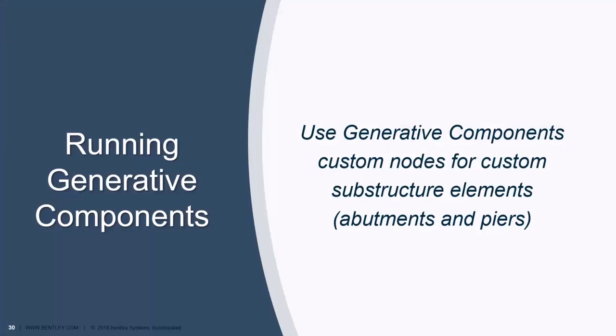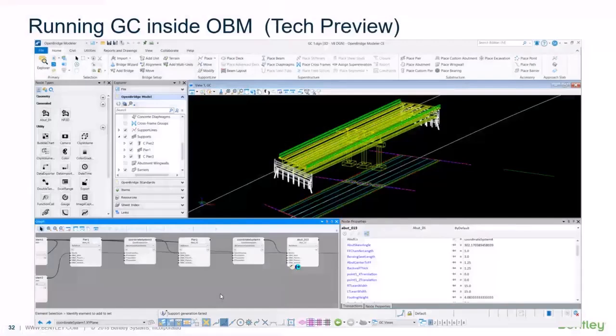They address a specific need, but then sometimes we put it to the test, and we realize that we need some extra stuff. And our answer for that in this release, in tech preview, is called Generative Component, or in short, GC. And basically, you can do whatever you want. It requires, I wouldn't say programming, I would say more logical thinking, a logical scripting tool. Don't get me wrong, you can put programs inside that tool, and little C++ routines if you want. But in general, it is just knowing the commands and connecting the logic in between.